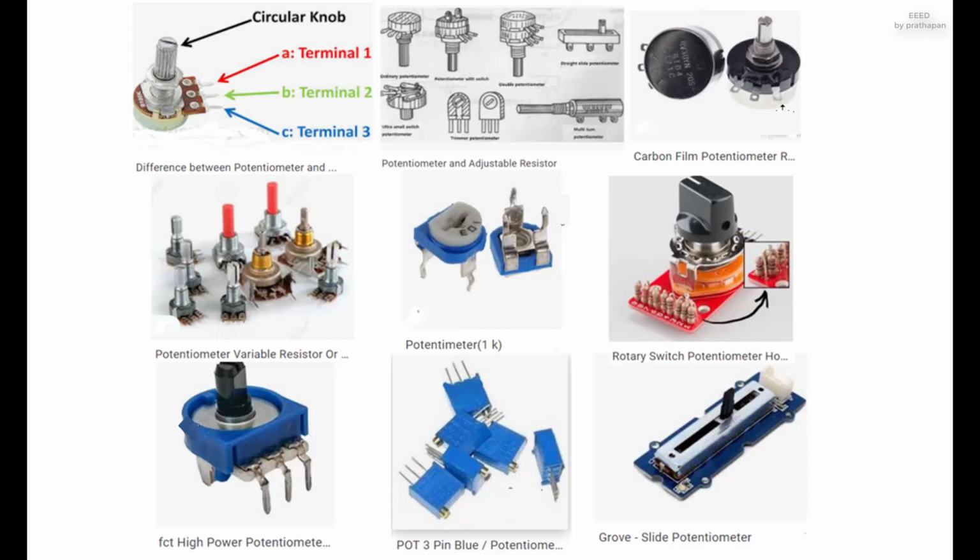Potentiometers are commonly used to control electrical devices such as volume controls on audio equipment. Potentiometers operated by a mechanism can be used as position transducers, for example, in a joystick. Potentiometers are rarely used to directly control significant power, more than a watt, since the power dissipated in the potentiometer would be comparable to the power in the controlled load.